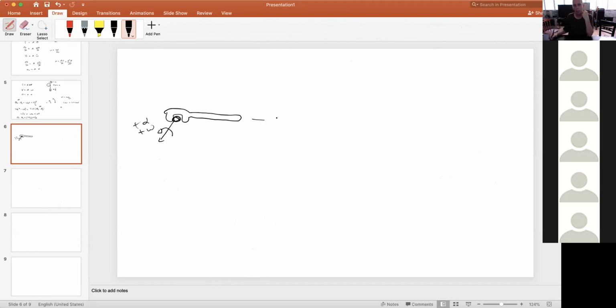Well, if you pulled on this wrench or you pushed on it, right, this thing wouldn't turn. So we call this the lever arm R, and it's the distance from where we apply the force. If that R and F were parallel to each other, nothing would happen. It wouldn't turn, right? You could, I guess, push it or pull it, but what has to happen is you have to have a force that at least has some component perpendicular to your lever arm.